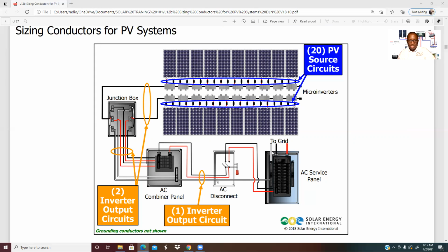So, negative, positive, connected to this circuit, parallel, this circuit, parallel. You notice that negative and negative is a negative from one series, one string, or one circuit to your junction box. Now, then we have the positive. Take the positive from each of those connections, moving over to your AC combiner box.